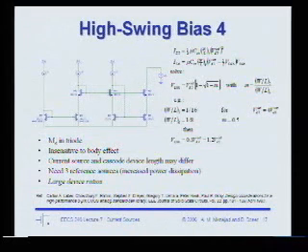You know, when transistors are close together, we know matching is very good. So if I'm using this and then I have another amplifier that's a few hundred microns away, the matching between those transistors is going to go to hell. So you might get into a situation where 3% of the parts fail because the voltage is too low and it drives your cascode into saturation, for instance.